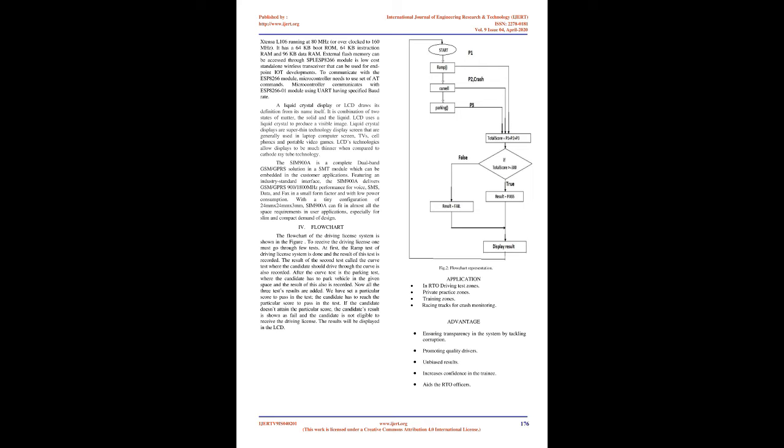An ultrasonic sensor is an electronic device that measures the distance of a target object by emitting ultrasonic sound waves, and converts the reflected sound into an electrical signal. Ultrasonic waves travel faster than the speed of audible sound. In order to calculate the distance between the sensor and the object, the sensor measures the time it takes between the emission of the sound by the transmitter to its contact with the receiver. The formula for this calculation is D = 1/2 T × C.